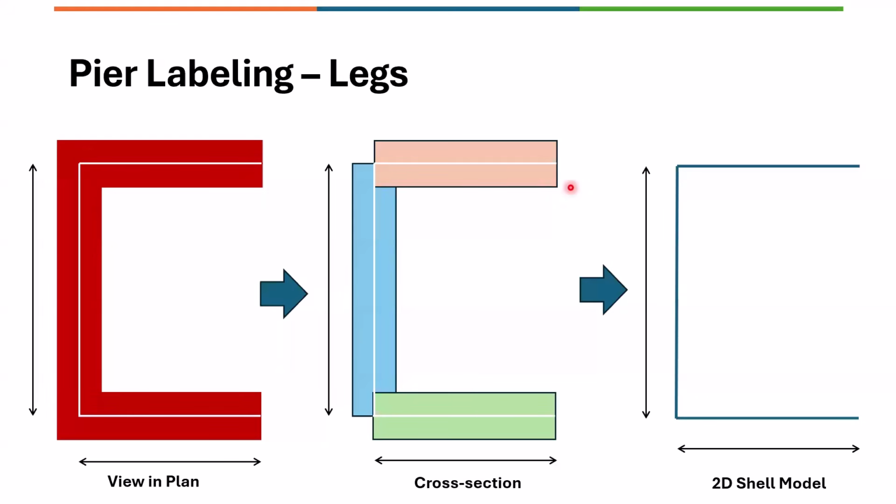So for the finite element analysis, it's a 2D shell element that we are using. So there is no thickness component as a 3D element. It is only the thickness property given to this. So what you see graphically is internally read as like this, the second image, the middle one, and then the actual finite element model is just a 2D area object, or the line if you see it from the plan. So the dimensions are measured to the center line. That's what you're seeing here as a representation.